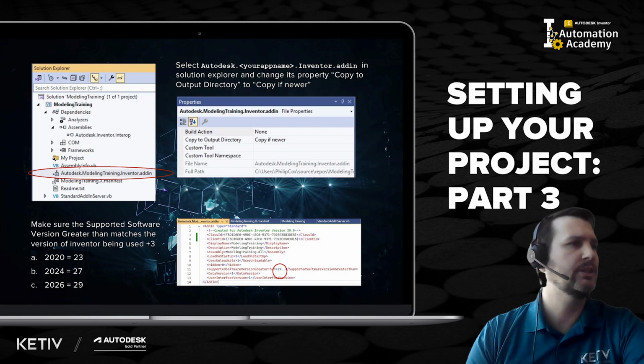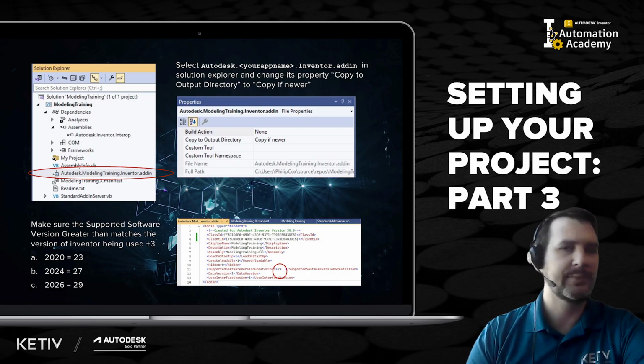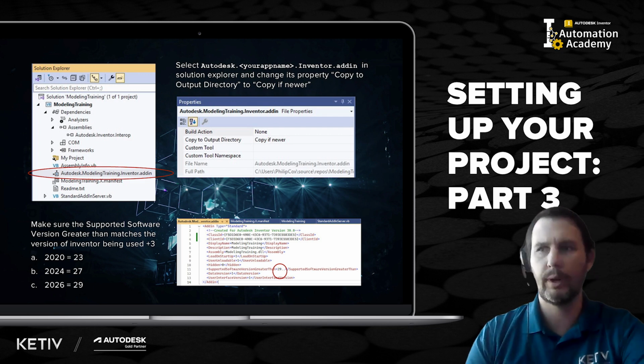So we'll just show you where that is, though it should be correct. We also have to change something on the properties of this file, this copy to output directory. We need to set it to copy if newer. If you don't do it, Inventor won't find your add-in. Happens to me all the time. I forget to switch that. So let's go do that. Go grab our Visual Studio.